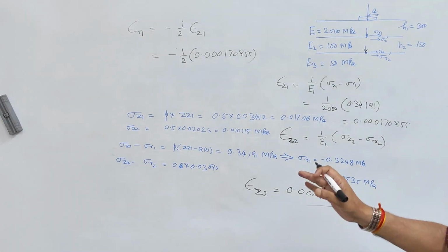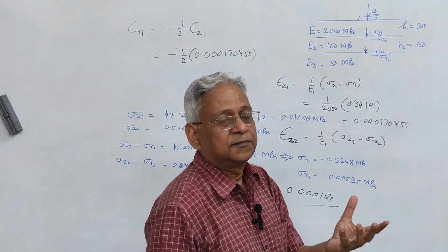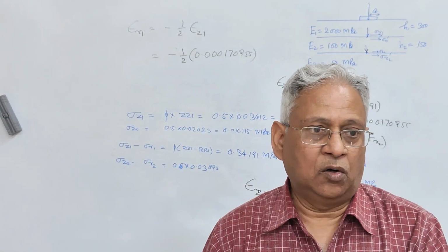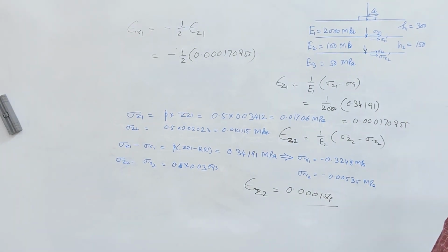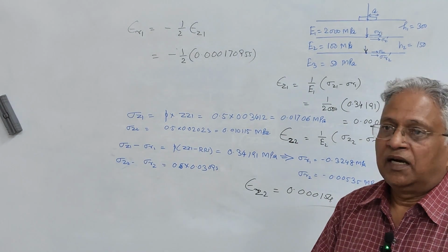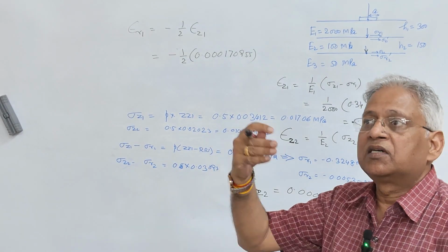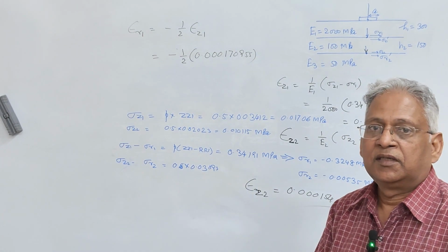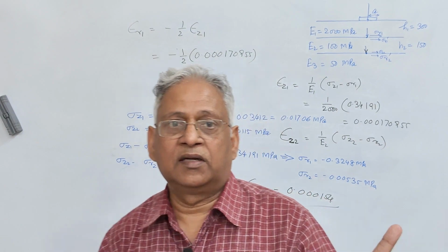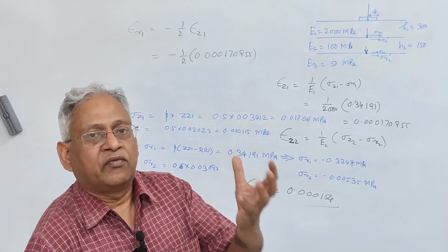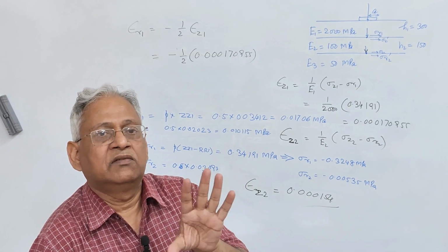Now if the value of E1 is changed, let us say instead of 2000 take 2500, then E1 upon E2 or K1 will not be the same as in the table, and in that case you need to interpolate the values, and to interpolate a single value you need 3 points. So your efforts increase by 3 times, and if all the 4 values are outside the values given in the table, then the efforts required will be 3 into 3 into 3 into 3, that is 81 times.